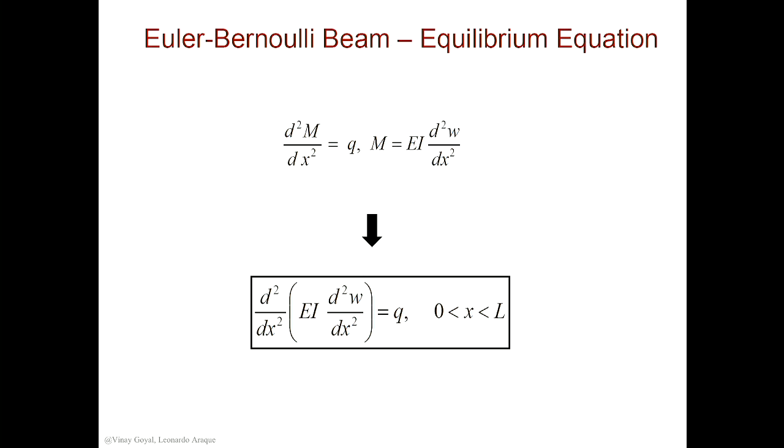And then we plugged in this relationship that we just derived into the Galerkin equation, and then we found the equilibrium equation for Euler Bernoulli beam. Okay, I also did this using the total potential energy, and then we worked the steps, and I showed you how basically by minimizing the total potential energy, I get the weak form, which is the weak form that you get by forming the weighted residual for this. And I'll show you what we've done before.